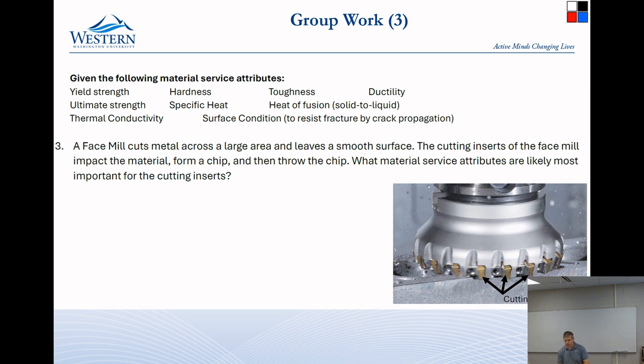What about these cutting inserts? Hardness, okay, so definitely hardness, because they are deforming another material out of the way. They are scratching and indenting and clawing their way through the material. So yes, hardness matters. Toughness matters, because they come around and they smack into the edge of the material. Now there's a problem. Hardness and toughness almost never go together. The harder a material is, the lower its toughness usually, because it becomes a brittle material and it doesn't absorb the impact very well.